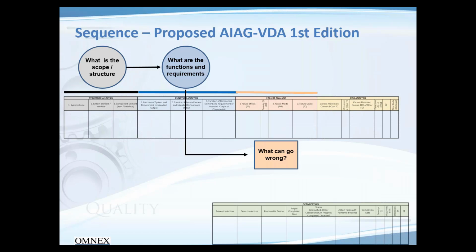Basically, the failure analysis will follow the function analysis in relation to how failures sequentially fail up into the system level. And you'll notice one of the changes is that the effects come before the failure mode. You'll see this where cause, failure mode, and effect are set up, and I'll show you how this works in the structure diagram.